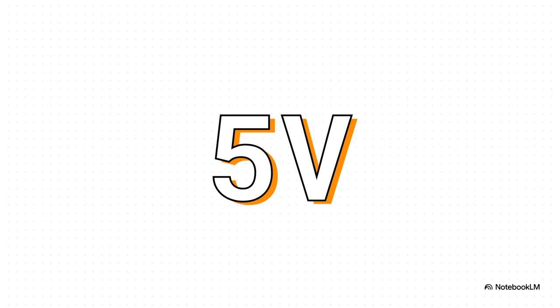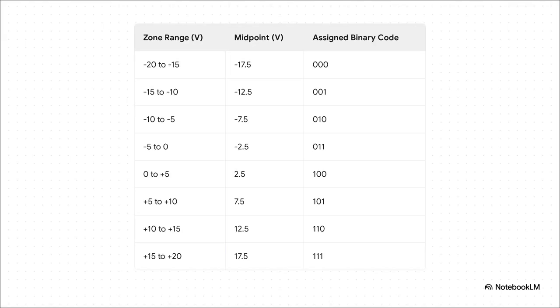Simple as that. And here's where it all clicks. So let's say one of our samples has a voltage of positive 8 volts. Well, that falls into the plus 5 to plus 10 bucket. So we just round it to the midpoint of that bucket, which is 7.5 volts, and we assign it the binary code 101. If another sample came in at negative 16 volts, it would get mapped to negative 17.5 and assigned the code 000. Every single possible measurement now has a clean 3-bit digital name.